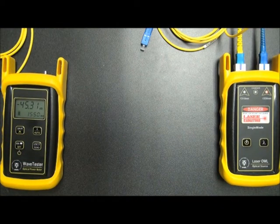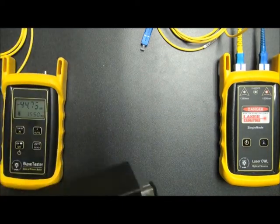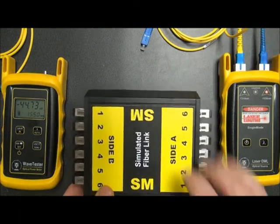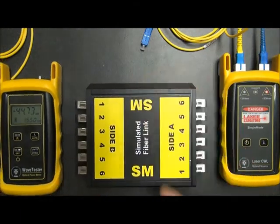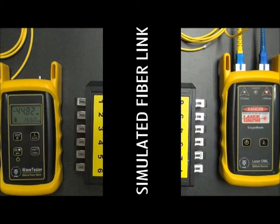Now, what I've done is I have this box here, it simulates a fiber link. In this case, it's simulating a 6-strand cable. There's a patch panel on side B and a patch panel on side A with 6 ports in it. The goal of this test is to test all of these fibers at both 1310 and 1550 nanometers.